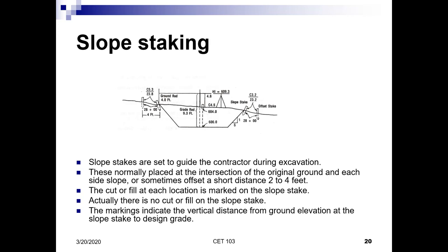Now, if you look to the left, you can see that we have a stake that they push out. The information that would be necessary to set a slope stake would be the distance that is desired at the particular center line or hinge point at which the elevation would change direction. We would also need to know the distance along the bottom of this roadway.